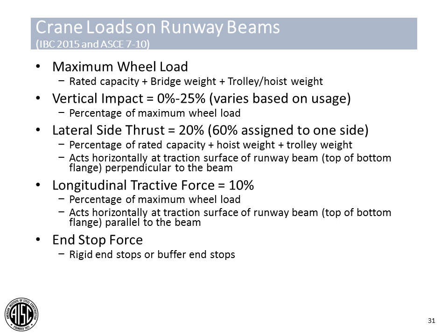This lateral side thrust load acts horizontally at the surface between the runway beam and the top of the bottom flange of the runway beam, and acts perpendicular to the beam itself.